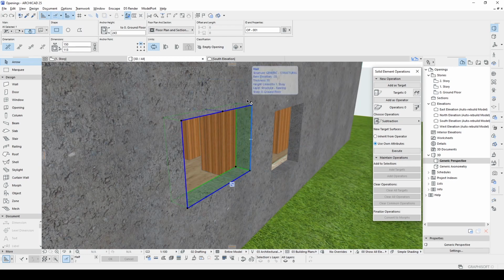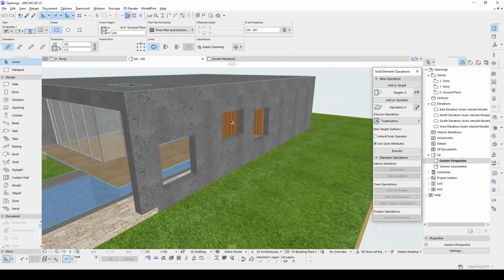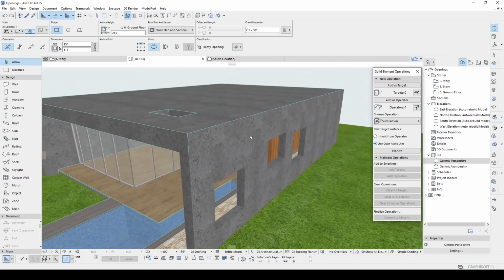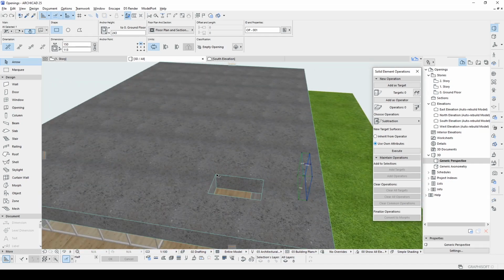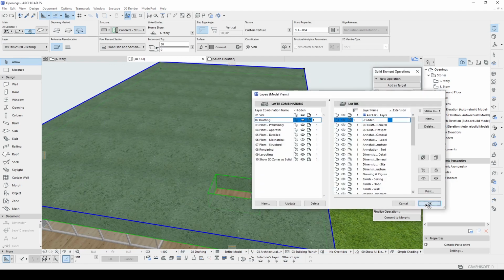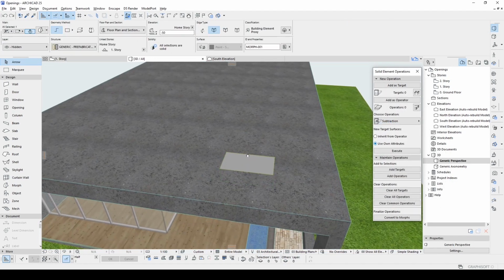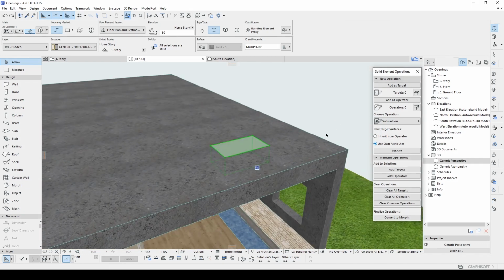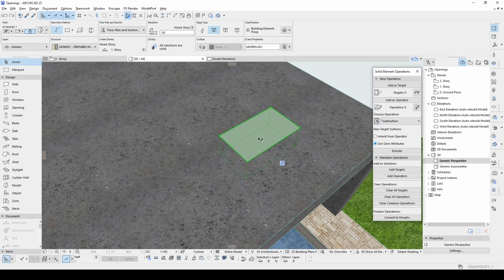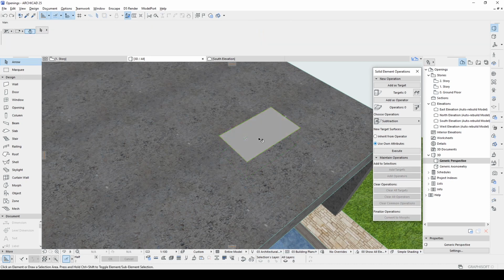It's very important. Why is it very important? We could create different designs if we can change the path of the extrusion length and create some shapes with that. Let's try that for this model. I'm going to make the hidden layer visible and select the morph, and I'm going to change the morph surface.